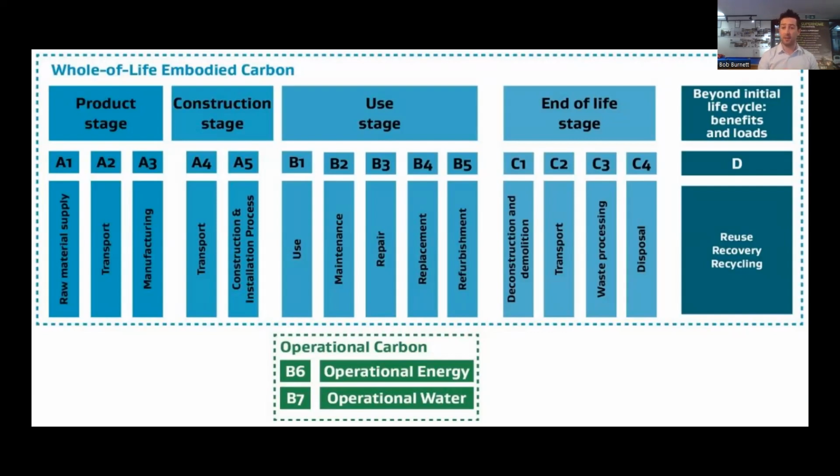So that is your material carbon cost, A1 to A3. A4 to A5 is going to be your transport and construction. B is the usage life of carbon from the usage life of that material over the life of the building. How does material still generate carbon when it's been installed? We'll take, for example, carpet. An example I like to always give is you might have 2 carpet options that you're looking at the start of the project. Carpet option A is lower carbon, but only has a 10-year replacement life. Carpet option B might have a higher carbon, but has a 15-year replacement life. So over the life of the project, over the space of 30 years even, you'll have replaced option B only twice, but the lower initial carbon one 3 times. So a life cycle analysis will help you tell which is actually the more optimal choice. In that case, it's probably the latter one.